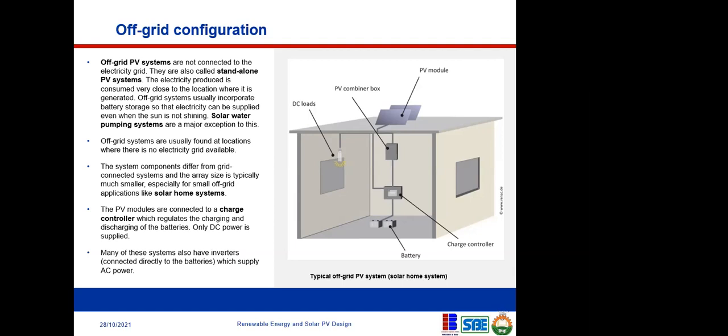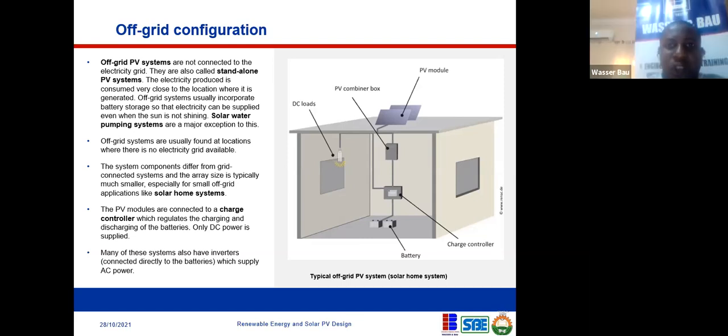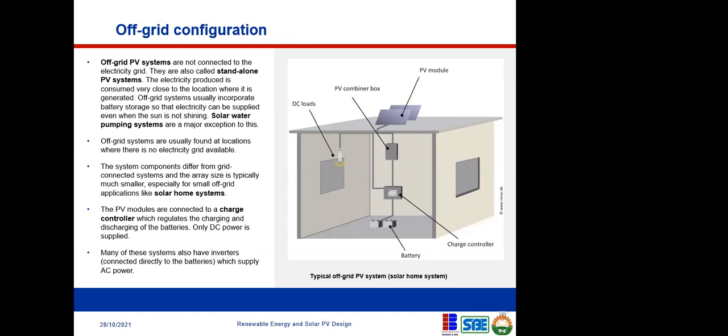Yes, your question is very valid. So in that case, please bear in mind that there is no one size fits all in this solar PV system. So it's on a case by case basis. For the case that you've situated now, yes, you have to make provisions for battery storage if that booster pump has to work at night. They have to make provisions for storage to provide power for it. And the energy consumption is very low, actually. So yes, I think it will work, but not like some of our submersible.